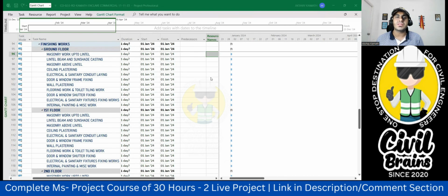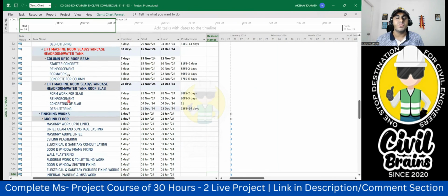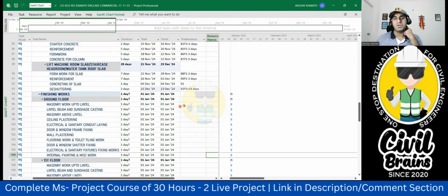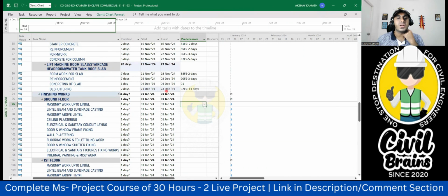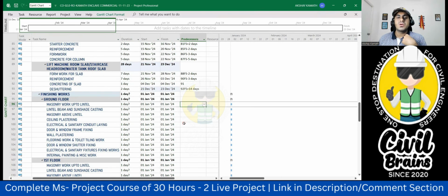Thank you. And before that, one assignment, not assignment, something you can do. Just imagine and tell me when you're going to start your masonry work up to lintel, because on 23 December you're finishing the de-shuttering work of your lift machine room. Now for masonry work, how are we going to give the activity? Concreting of the slab will happen on 4th December, right? So 92 FS minus something, think how we are going to do it. Whether you want to give the connectivity of 92, 4th December I'm finishing, 15 days before that I'll start my masonry work up to lintel. So think about when the start date will be for this particular activity, and how many days are required.